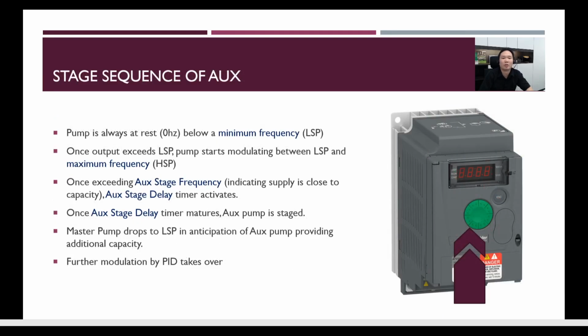Right. So let's talk about the stage sequence of the auxiliary pump. When I say stage sequence, it means that our demand is exceeding what the primary or the master pump can provide, so it has to call for a backup. Okay. So during normal operation, the pump is always at rest below a minimum frequency.